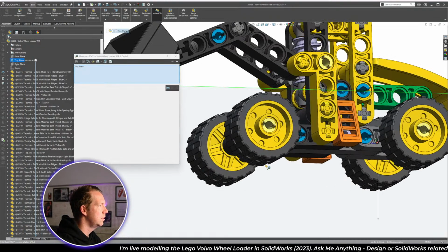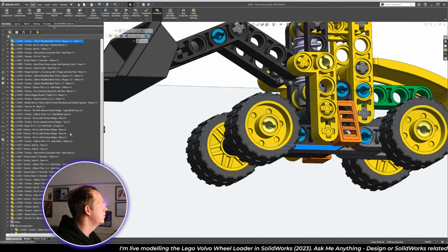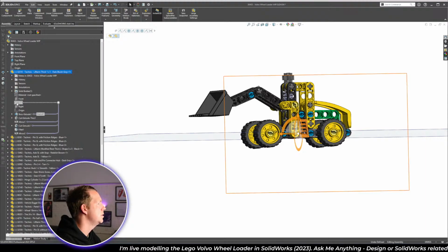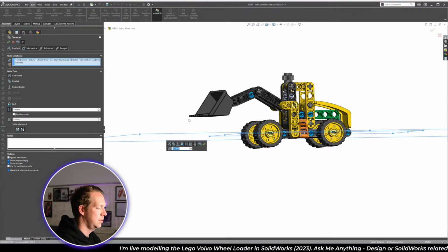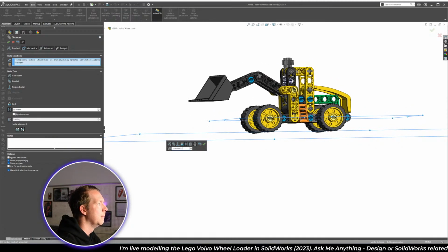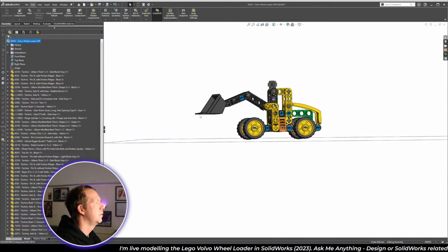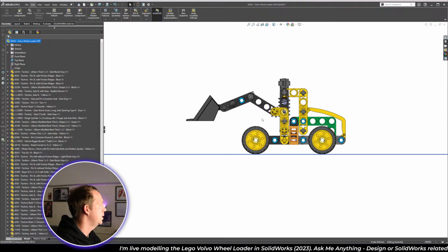So these wheels are 23.6 in diameter. So if I move this part up half that dimension by getting the front plane and the top plane mate distance, 23.6 divided by 2, that should put it in the exact place that I want it. See that front plane now, or that top plane? It's running right where our wheels should be.